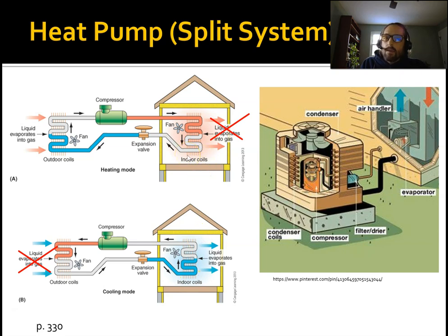And then the nice thing about a heat pump, again, is that you can heat and cool with the same equipment, and you just have that reversing valve, which then reverses the flow. Okay, and these coils, inside and outside, nothing changes for them. It's just static. It just stays there. But the refrigerant flow changes, and it converts the evaporator. What was the evaporator coils? You reverse the flow, and now they become condensing coils, or condenser.